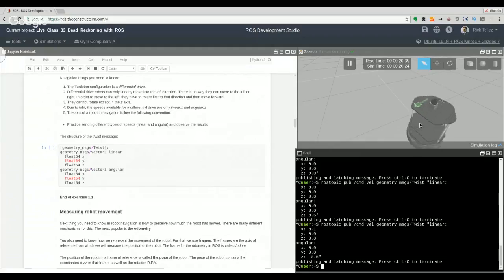But at some point you have a bug, and that code crashes, and the control of the velocity and the direction of the robot is not usable anymore. Then you have to have something that says, hey, if I'm not receiving a message every 10 milliseconds, then I'm going to stop the robot, because that means the control program has died. That's a safety measure.